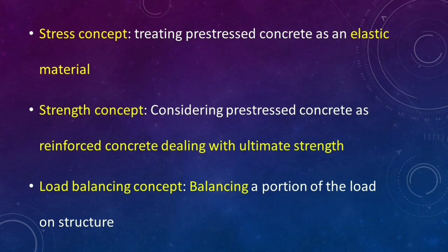So, as a whole, we dealt with three concepts: the stress concept, in which the prestressed concrete is treated as an elastic material; the strength concept, in which the prestressed concrete is considered as reinforced concrete dealing with ultimate strength; and the load balancing concept, by balancing a portion of load on the structure.